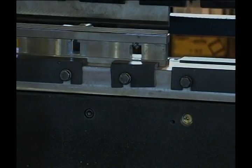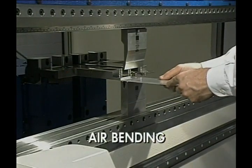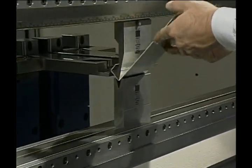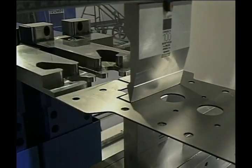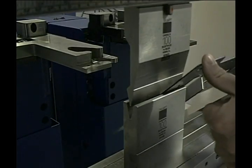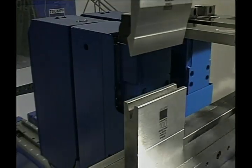Press brake bending is divided into 2 major categories: air bending and bottom bending. In air bending, the punch and the workpiece do not fully bottom on the female die. The workpiece, supported by high points on the die, wraps around the tip of the punch to form the bend. Air bending is highly versatile, since a large variety of bend angles can be made from a single set of dies. Another advantage of air bending is that it requires considerably less press brake force to produce a bend, 4 to 6 times less than in bottom bending.